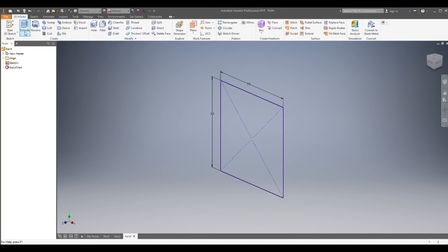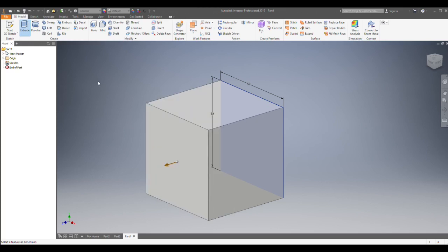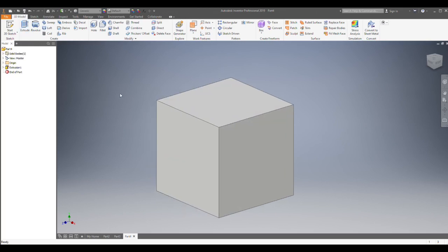Now what I'm going to do is I'm going to make this 3D using Extrude. If I click Extrude, it automatically recognises that this is what I want to change. So I want to make this 3D. If it doesn't do that, then just hit Profile and then click the shape, and it'll give you what I've got on the screen here. I'm going to make this 50, so that's a perfect cube, and I'm just going to hit OK.